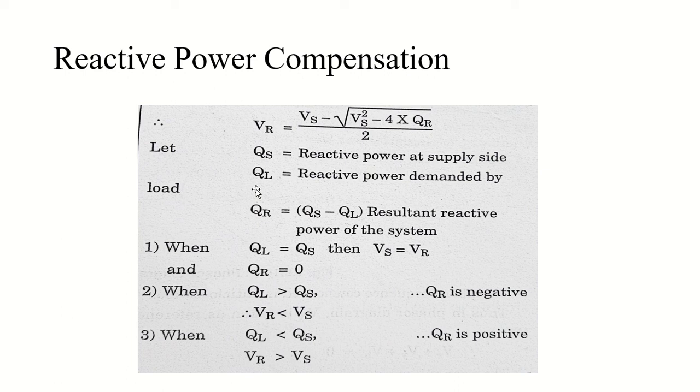And when that happens, VR will be less than Vs, because remember I've said reactive power always flows from higher magnitude to lower magnitude.